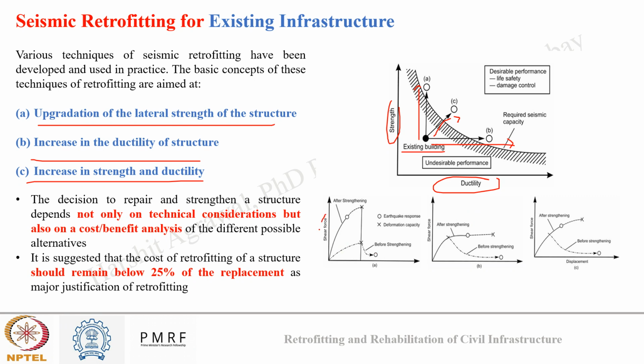Okay, so you can see here, if we just opt for strengthening, the shear strength of the building is increasing, and there is minimal drift in the building. And if we do a ductility increase, the shear strength will remain the same, but upon earthquake action, the structure's response to the earthquake without enduring damage will improve. So the ductility performance of the structure is increasing, which will help it survive the earthquake damage.